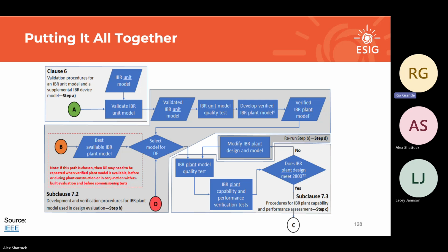The low voltage is a fault and then a slow ramp back to 0.90. The high voltages, the profile we all are used to seeing. Faults don't look like that, right? So the point of the model quality test is not to replicate the grid or show grid stability. It's to show that during those crazy extreme events, things aren't breaking. So it's more like a stress test in the software world than it is a performance test.